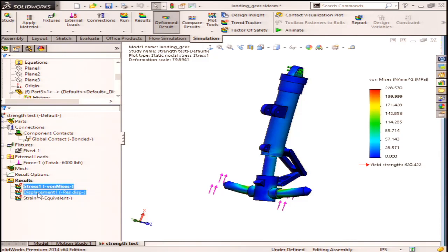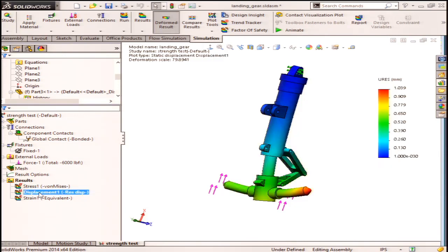So that can happen where you don't have a converged answer for stress, but displacement is something we're actually measuring. So you can have convergence of your displacement without convergence of your stress. I just wanted to point that out. That'll happen at something like a singularity point or a corner where you don't have a fillet. Try to avoid stress concentrations if at all possible, but I'm sure you guys know that.